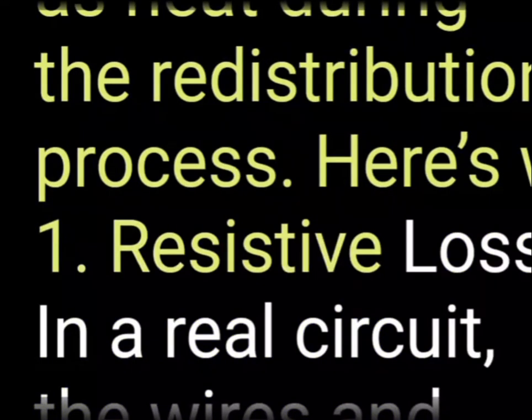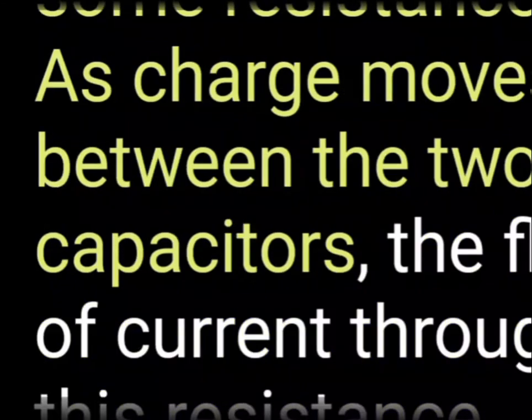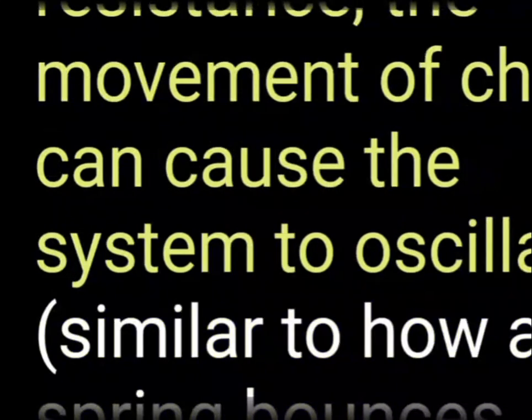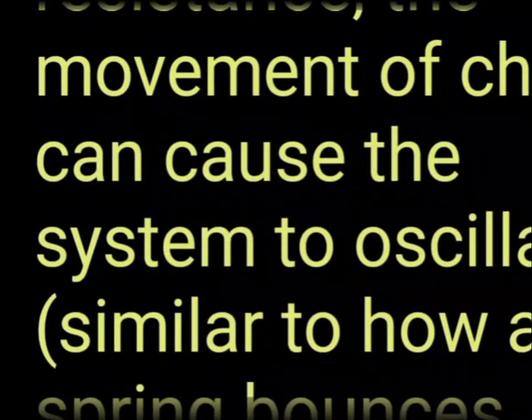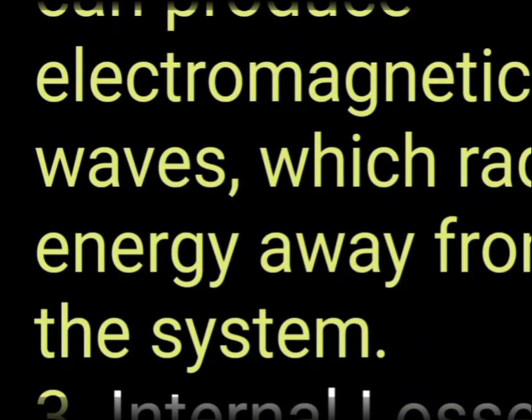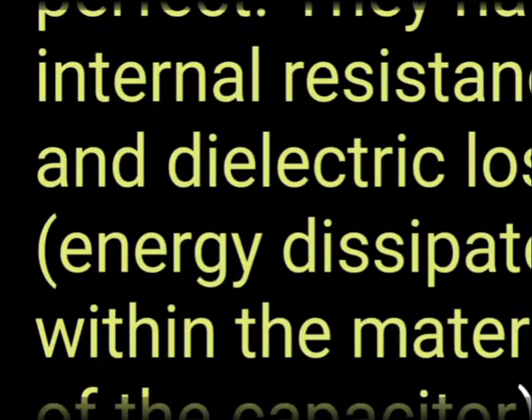Here's why. 1. Resistive losses. In a real circuit, the wires and internal parts of the capacitors have some resistance. As charge moves between the two capacitors, the flow of current through this resistance generates heat, which dissipates energy. 2. Electromagnetic radiation. Even if there's no significant resistance, the movement of charge can cause the system to oscillate, similar to how a spring bounces back and forth. These oscillations can produce electromagnetic waves, which radiate energy away from the system. 3. Internal losses in capacitors. Real capacitors are not perfect. They have internal resistance and dielectric losses, energy dissipated within the material of the capacitor, which also contribute to energy loss.